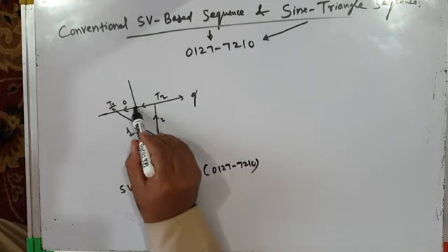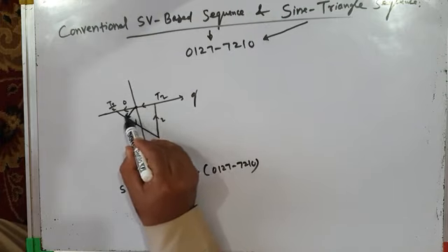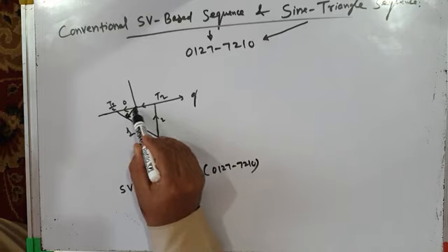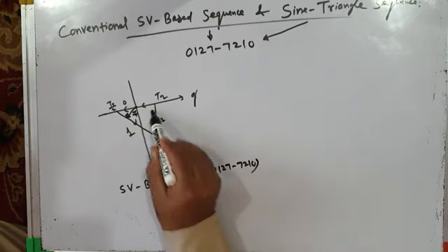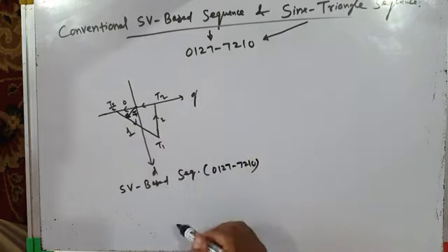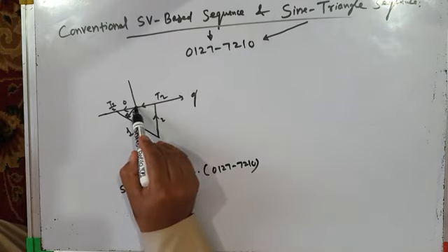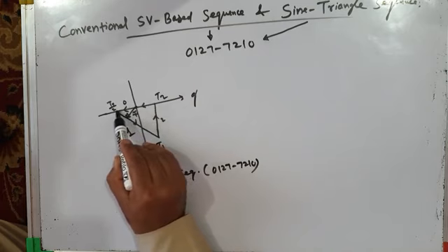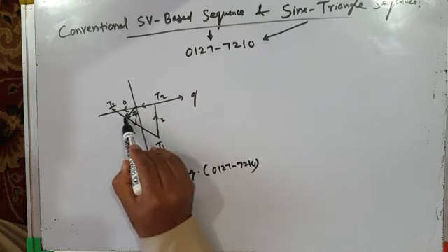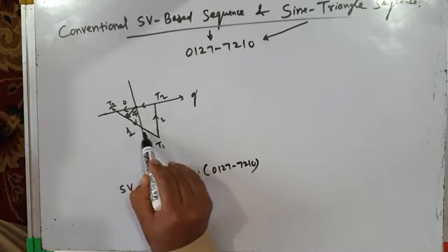So therefore your stator flux ripple, this is your stator flux ripple psi tilde, it moves along this triangle when 0, 1, 2, 7 sequence is used in a subcycle. In subcycle it moves like this. When null vector is applied, it moves along this line. When active vector 1 is applied, this stator flux ripple moves along this line.